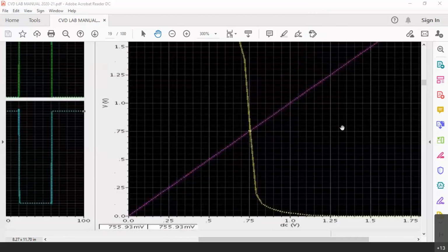Actually, holes will not move at all. Holes are stationary charges. Electrons have to move to fill the holes there. Only electrons can move. Holes cannot move because holes are the vacancies in the atomic orbits. So electrons have to come from elsewhere, they have to occupy the holes. That is why always the mobility of holes is lesser. In this particular VLSI process, mu n is 2.2 times of mu p.